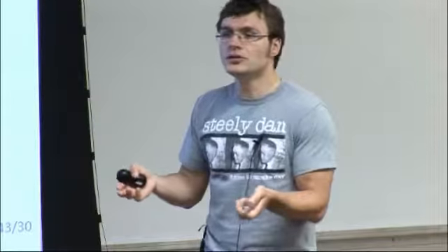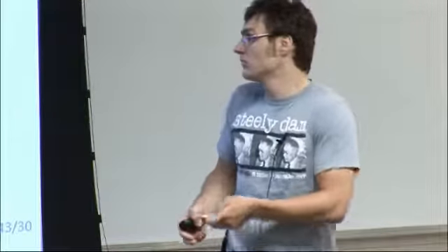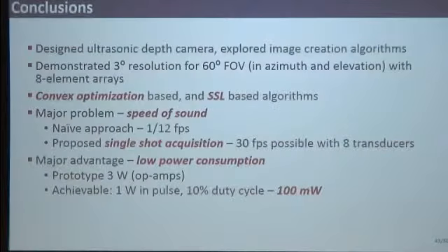But if you do the design specifically for these transducers, you could achieve something like, for the 8 transducers at once, 1 watt in pulse. Okay? And perhaps 10% of duty cycle. We're not using them all the time. This results in maybe 100 milliwatts of power consumption.